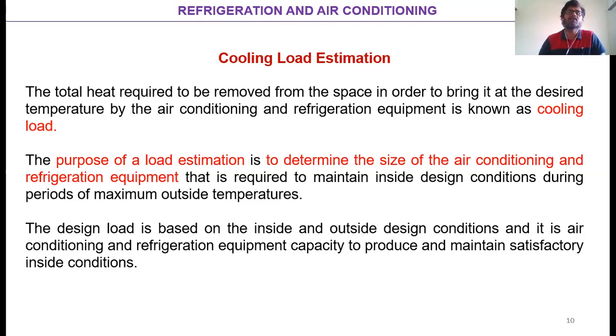So that is what we are saying here, the total heat which is required to be removed from the space, which is nothing but the load which should be handled by the refrigeration or the air conditioning equipment, the load on the system. So what is the purpose of this cooling load estimation? The purpose of this load estimation is to determine the size of the air conditioning and the refrigeration equipment.